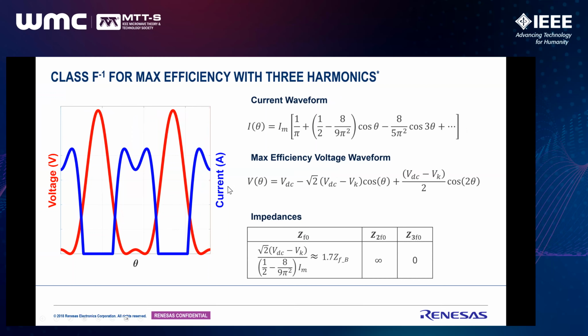Well, the catch again, as Joe was presenting at the very beginning, is that by introducing this second harmonic voltage component into the voltage waveform, we are actually peaking the voltage. That way, it's almost 2.9 times the VDD. So definitely, the breakdown voltage of the device has to be higher than VDD by 2.9 times. Otherwise, that's the catch, inverse class F PA cannot be realized either.